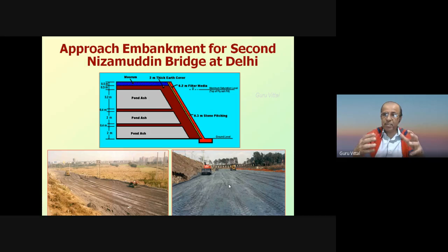To back dump gravelly type material and to construct the embankment within the water will involve huge cost, because gravelly type material is costly and a huge amount of wastage will be there when we back dump it, because it will not fall exactly in the place we are intending. So it will spread out. The cost of back dumping the gravelly material within the water and then constructing the embankment over it will be very huge. Unfortunately, in this particular instance, we had no other option.